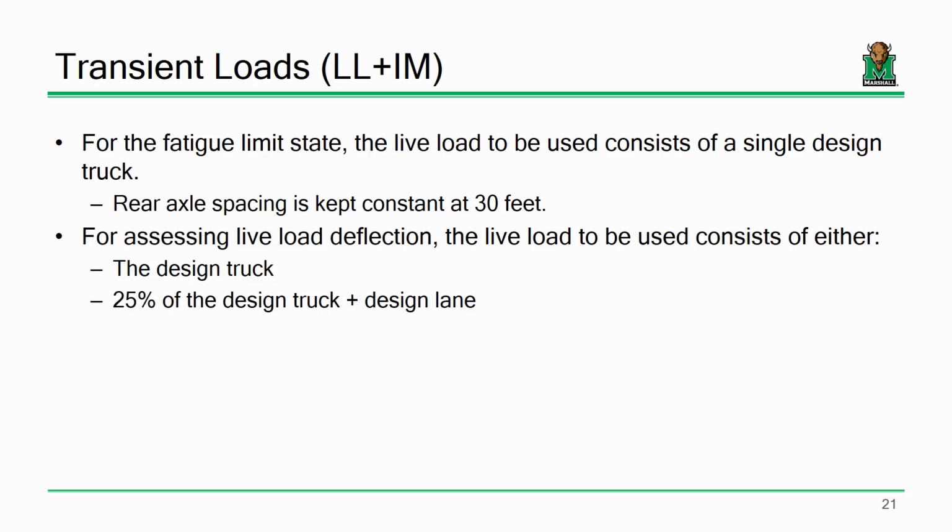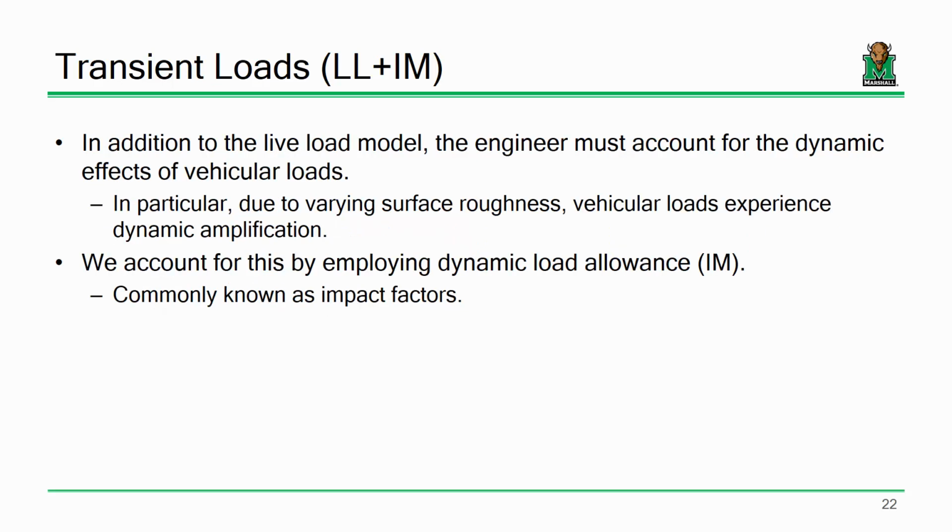When we do live load deflection checks, we use either the truck or 25% of the truck plus the lane. And that's just the code specified provisions for preventing exceeding maximum allowable deflection. So the truck or the 25% of the truck plus the lane. Okay.